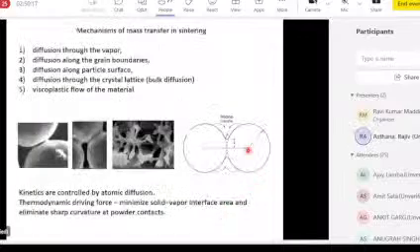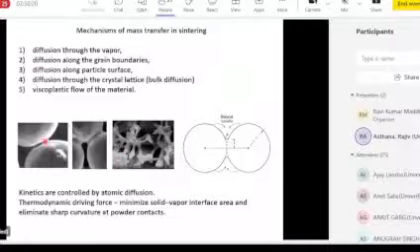And during sintering, there are a lot of fundamental material processes taking place. There is no melting taking place during sintering most often. You want solid state diffusion to form necks between powder particles, and those necks form by diffusion and viscoelastic flow in the contact region. So diffusion is promoted in the contact region because of curvature effects, basically the Gibbs-Thomson effect,